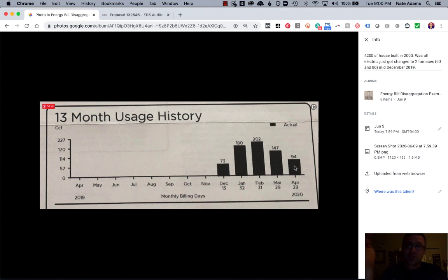When you get to 0.5 to 1, so if a 4,200 square foot house was using 2,100 therms, that's still pretty bad, because 2,000 therms is a lot of gas. My old 1835 barn used 1,500 to 2,000 therms of gas a year, and I very seldom see a house over 3,000, even when it's a bigger, older brick house in the near outskirts of Cleveland. So 0.5 to 1, 2,100 therms, would be bad. When you get down to a quarter to 1, so this house using 1,000 or 1,100 therms, that's pretty good.